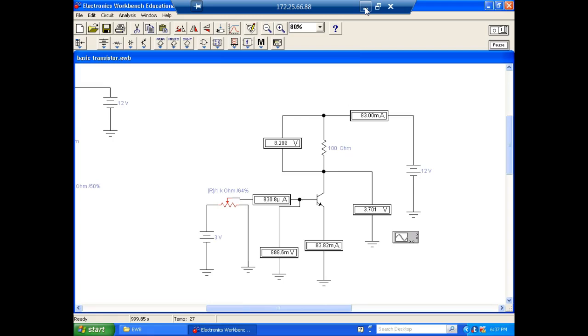We'll look at why. We'll talk about what we call impedance matching and all this other kind of stuff. We'll learn a lot of why things are the way they are in this class. So this is called a common collector, and this is the common emitter. This is the most widely used amplifier out there. For saturated switches, this is the guy. Common emitter is what's used for saturated switches.